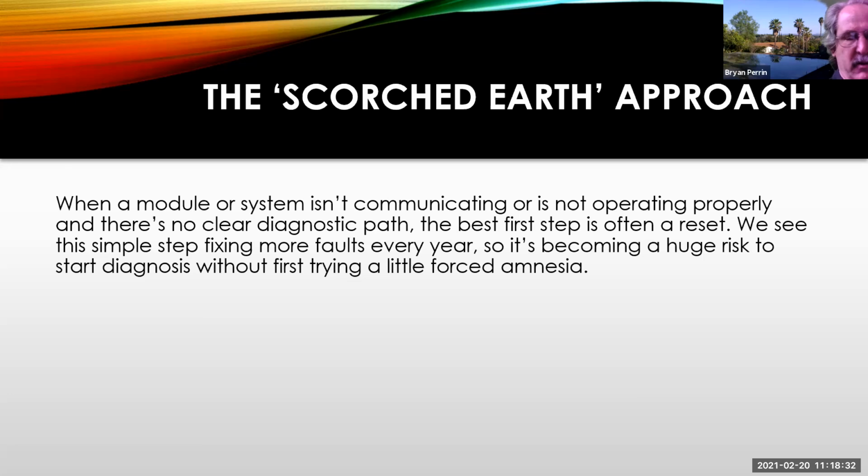I'm glad. There's also what we call the scorched earth approach. When a module or system isn't communicating or isn't operating properly and there's no clear diagnostic path, the best first step may be a reset. We see this simple step fixing more faults every year. So it's becoming a huge risk to start diagnosis without first doing some forced amnesia.